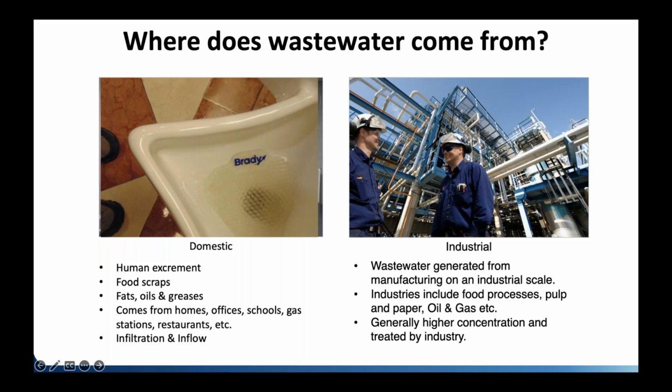Generally speaking, it's treated by the industry, but there are a lot of instances with lagoons where that industrial waste is getting mixed in with the municipal waste and going to the municipality to be treated. And so that's where it becomes of concern for the municipality. It's usually a higher concentration of everything, BOD, ammonia, it'll be all across the board. There'll be some pretty crazy concentrations associated with this type of wastewater.